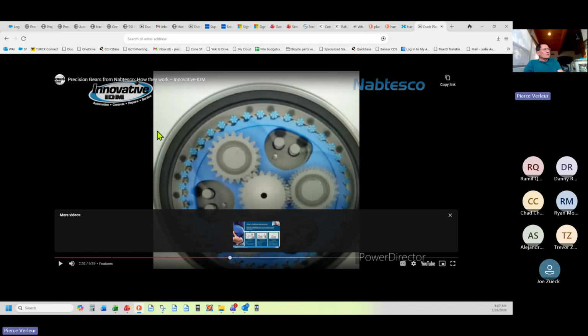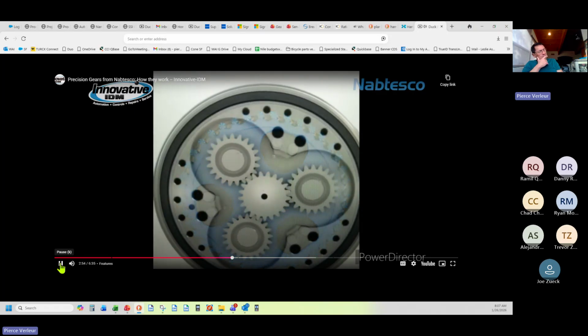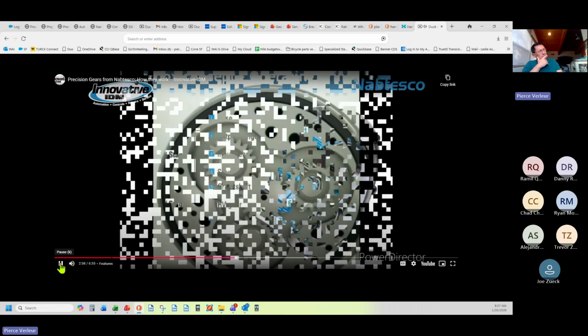What I wanted to point out is that we don't necessarily need this to obtain the gear ratios. We will direct drive this disc with the servos in the Cone design. So that's an advantage over Tesco's design. So let's get down into the specifics as far as how cycloidal gearboxes work for those who would like to know.